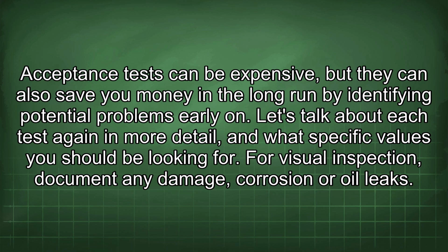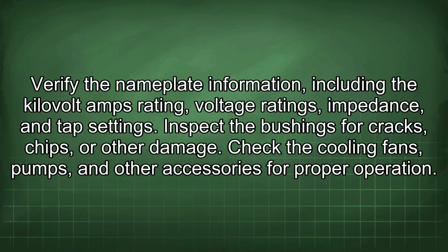For visual inspection, document any damage, corrosion, or oil leaks. Verify the nameplate information, including the kilovolt amps rating, voltage ratings, impedance, and tap settings. Inspect the bushings for cracks, chips, or other damage. Check the cooling fans, pumps, and other accessories for proper operation.